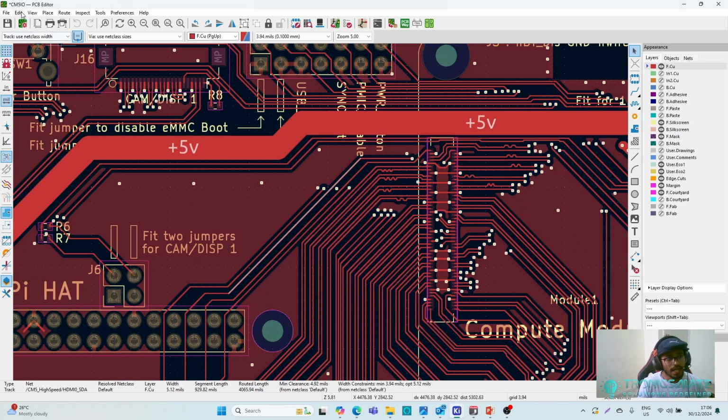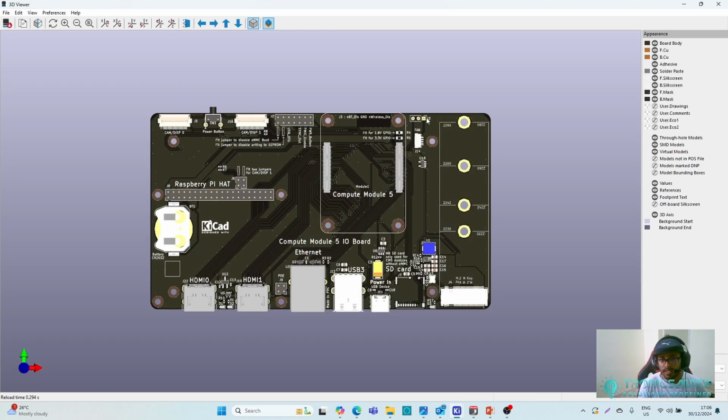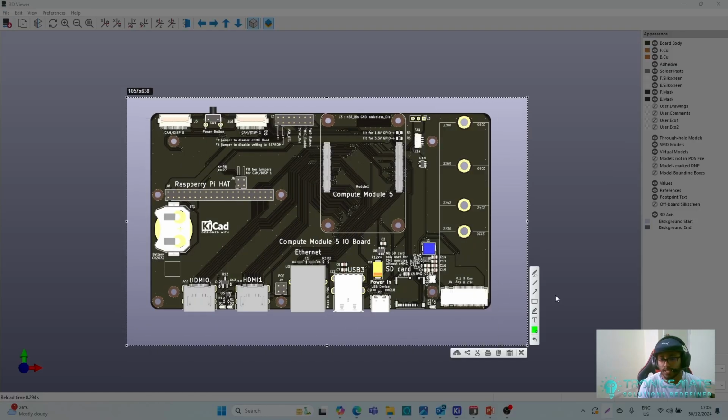Other than that, I don't have much to discuss about the PCB design. Other things you can place as you want, but it is always better to keep them organized. Like here, the power supply is for M.2. So you can see everything related to M.2 is pretty much close together. Like that, it is good practice.